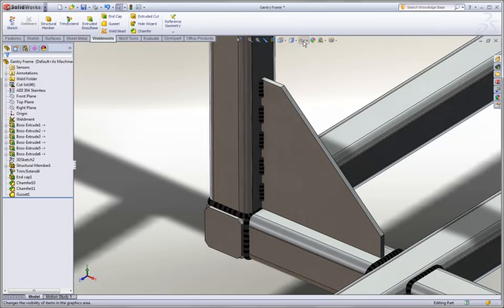One thing we haven't seen while we've been adding these are the annotations that are created. You'll notice that for every weld, SolidWorks creates the appropriate weld note annotation. It not only includes the weld symbol and the weld size, but also the weld length, the staggered value, and even the staggered annotation on the note.